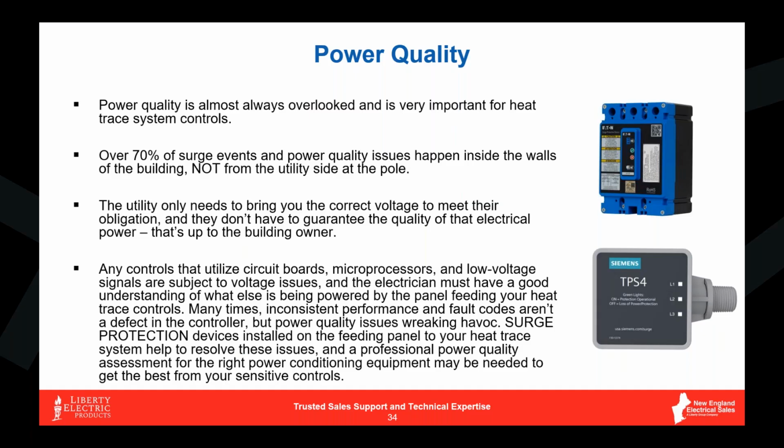The other thing I remember was that they said, hey, look, the utility really just needs to guarantee the voltage to your building. It doesn't have to guarantee the quality of that power getting to your building, which is true. So whenever you have microprocessor-based controllers, you should be thinking hard about power quality, in my opinion. Generally we don't have these issues, but it has happened before. Typically when you see things like blinking episodes or chattering on the controller, it's generally more of a facility power quality thing than the equipment itself.